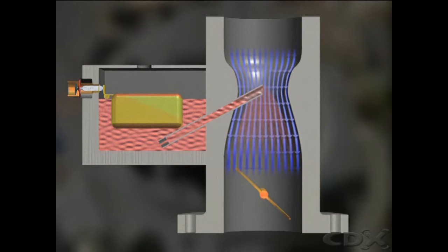Fuel is pumped to the float bowl, where a float and a needle valve control its level. The float bowl is open to the atmosphere. The barrel of the carburetor has an air horn and a venturi. A throttle valve below the venturi is linked to the accelerator pedal. Its action allows airflow into the carburetor barrel.